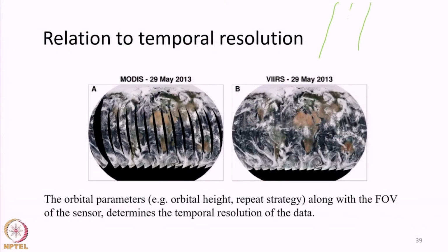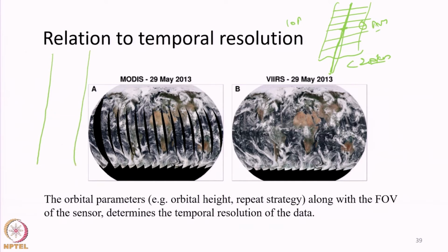Like this is the swath width, the center line is the nadir trace of the satellite, this is the exact line over which the satellite is overpassing, this is the swath width. If this is very narrow, in the order of 200 kilometers, we can assume the same time. Say here the time is 10 am, here also we can assume it to be 10 am. Let us take the example of MODIS. This is the nadir trace of the satellite orbit. Swath width will be something like this, in the range of 2300 kilometers.